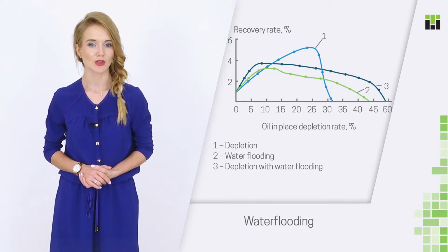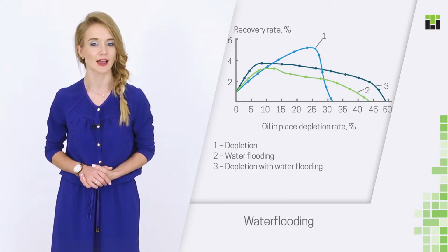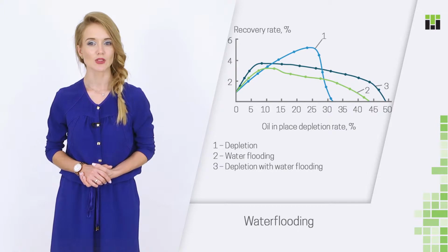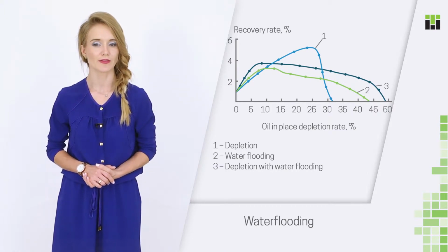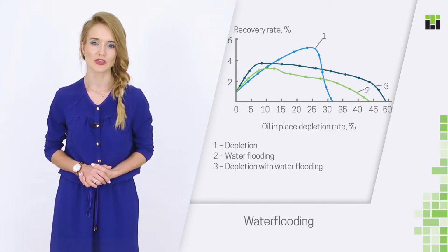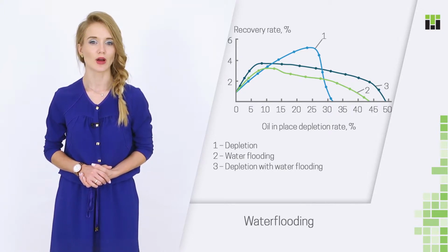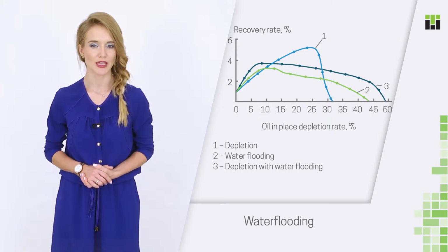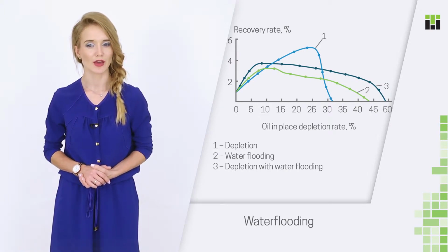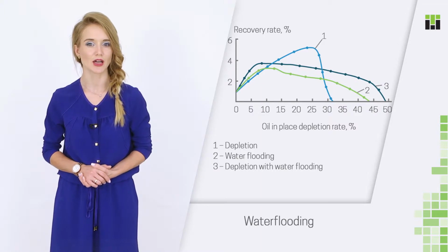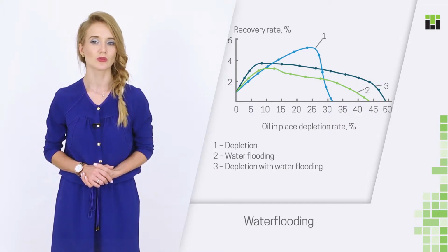Since the early days of petroleum industry and until the 1940s, companies developed oil fields using depletion drive. That was not quite efficient as oil recovery usually was below 25%. Occasional natural water drive helped a bit where it was available, and for secondary recovery people injected air, sometimes mixed with other gases. They also used the so-called vacuum process. Then gas was literally sucked out of production wells, followed by oil.